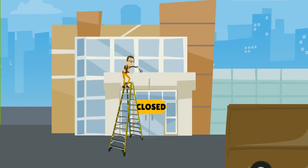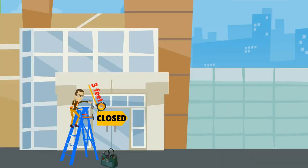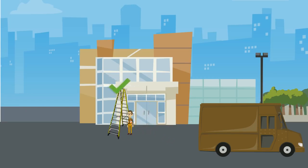If your knees are above the top of the stepladder, you are too high on the ladder. Use a stepladder that is about 1 meter or 3 feet shorter than the highest point you have to reach. This gives you a wider, more stable base and places the shelf at a convenient working height. Place a stepladder at right angles to the work, with either the front or back of the steps facing the work.